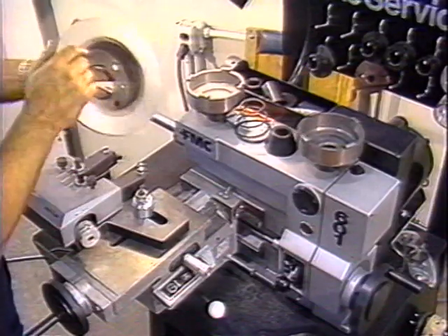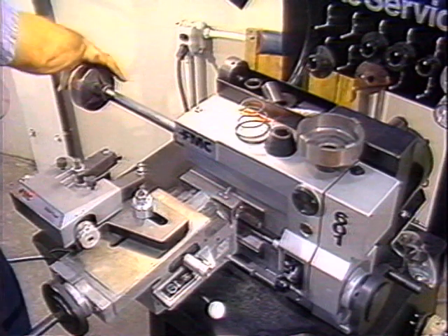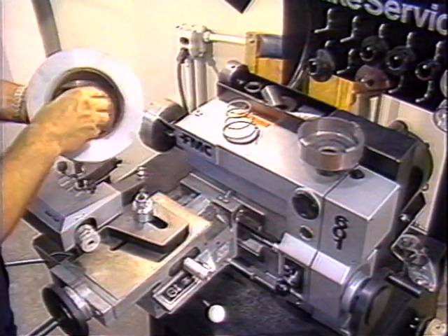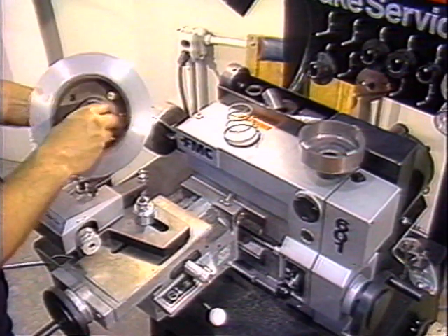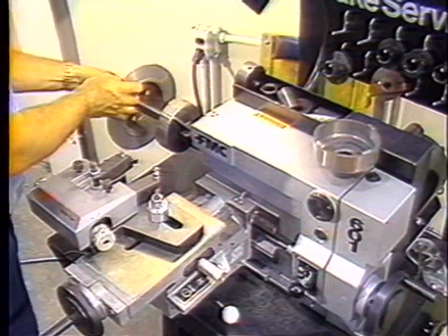Place a silencer band of the appropriate size on the rotor, or use the clip-on silencer if you're working on a solid rotor. Before mounting the hubless rotor, ensure that the entire rotor has been properly cleaned and is free of dust and road grime on the inside surfaces.